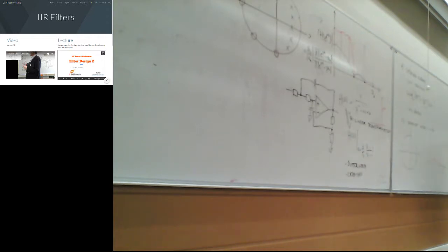So Nyquist frequency here. So basically what you would do is to take this frequency of whatever that is, our noise frequency, and the corresponding angle, the omega n, and put a notch here, meaning the amplitude response goes to 0 at that point. Ha! Problem solved. Kind of, sort of, but it looks ugly.